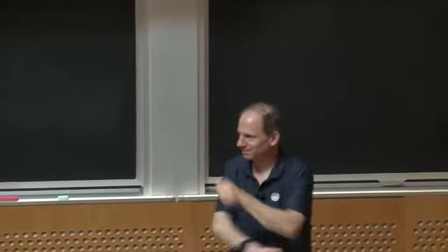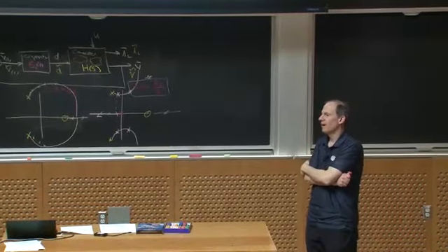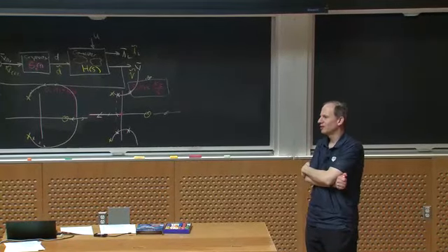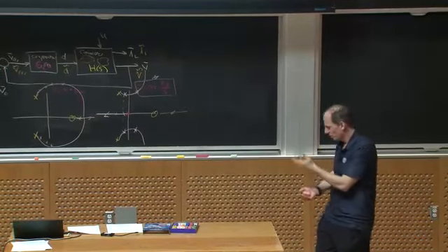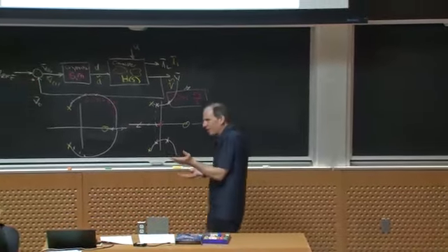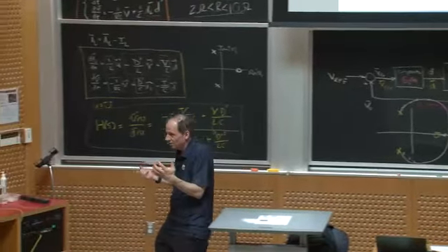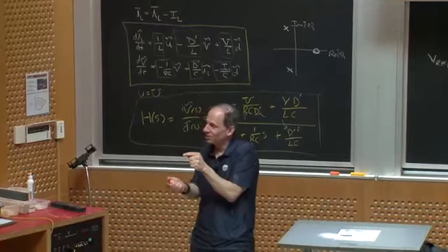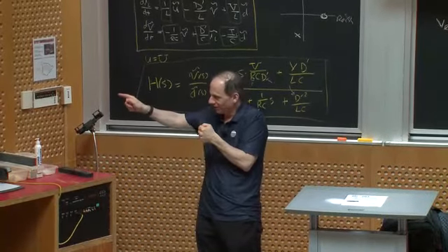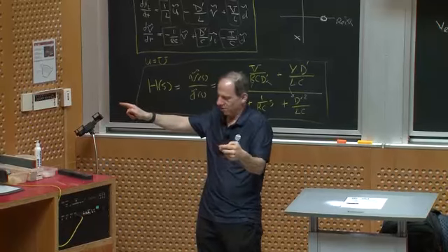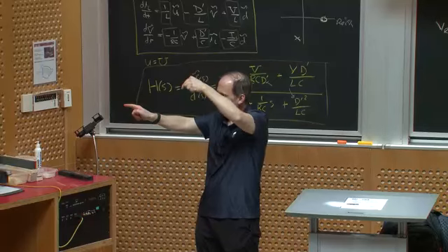Sort of like what devices would require a more stable output voltage? If you were building a power supply to feed a sensitive instrumentation amplifier, for example, right? Because if you have some instrumentation amplifier that's picking up some tiny signal, for an EKG or whatever it is, that amplifier has some power supply rejection ratio, meaning the output of the amplifier will give you the response to the input, but there's a tiny little response to the power supply variation.